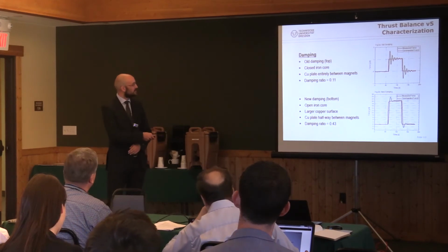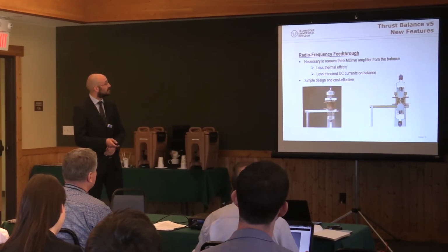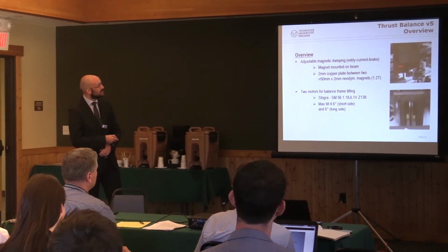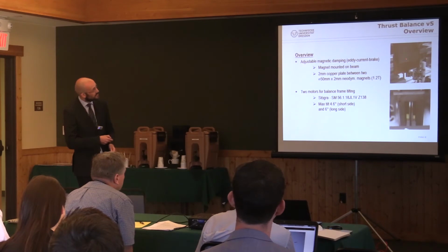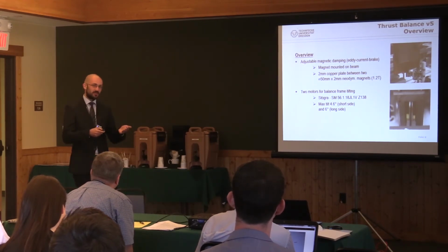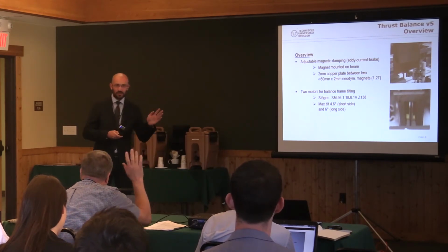I could increase it still because if I go back a little bit, if you see here, this is actually the point for damping. So I could slide this copper a little bit more into the magnets to increase the damping even further. And if I have time, I will try this. And like I said, I want to aim for 0.7.